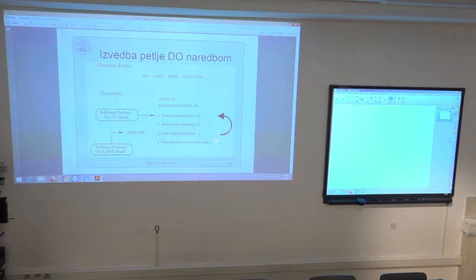And furthermore, with a conditional jump, you would also have a pipeline stall. As I described previously, all of these architectures are based on an instruction pipeline. And if the program counter is not sequentially incremented, then the address that was fetched in the fetch part of the pipeline was the wrong instruction, because it had to branch back to the first address of the loop. And normally with a conditional branch, you would have this stall.